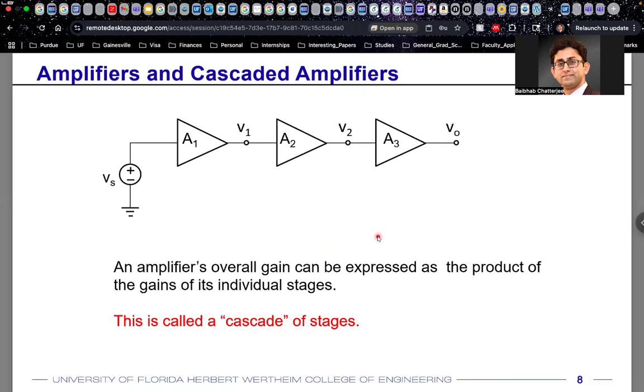Just to clarify, when it reaches that point, that means it's hit the VCC potential, right? Exactly, you're correct that if it reaches VCC, then it will definitely get flipped. But in real amplifiers, even before it reaches VCC, it starts getting flipped. So this occurs even before it actually reaches VCC. And there are reasons behind that which we'll learn later in the course.